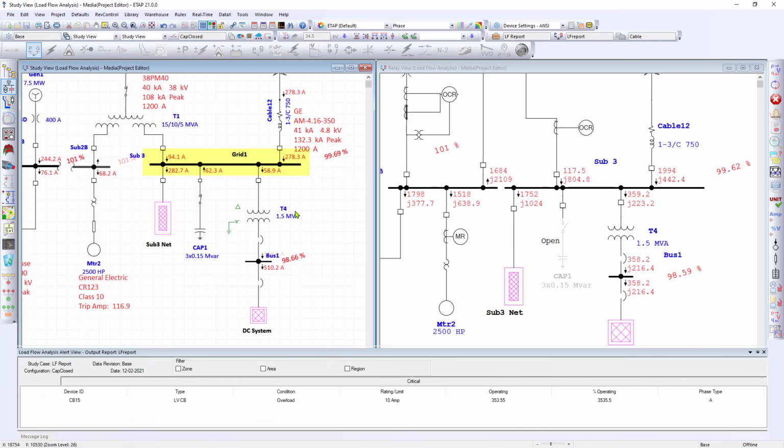I can run my load flow and instantly compare side by side with a quick configuration change and do quick what if scenarios and look at the results without creating any new databases or project files. I can simply use the same project, the same one line, one with relays hidden and the other with the relays exposed, and then we can quickly compare the results of these two different conditions. And you can easily manipulate your model again in toggling all your protective devices and switching using the keyboard shortcut T.